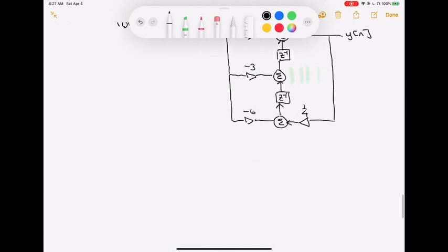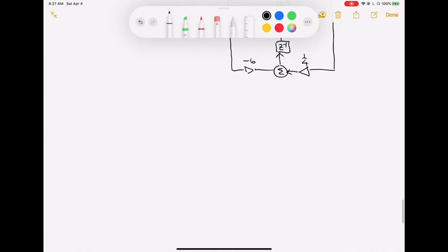Okay, so let's look at some other ways of doing this. Let's do a series realization and let's do a parallel. Usually you wouldn't do this with a second order system. I'm just picking a low order one so we can get through it in a timely way. But the basic strategy here is always about the same. So we had an H of z, and that H of z was equal to 3z squared minus 3z minus 6 over, in this particular case, z squared minus 1/4.